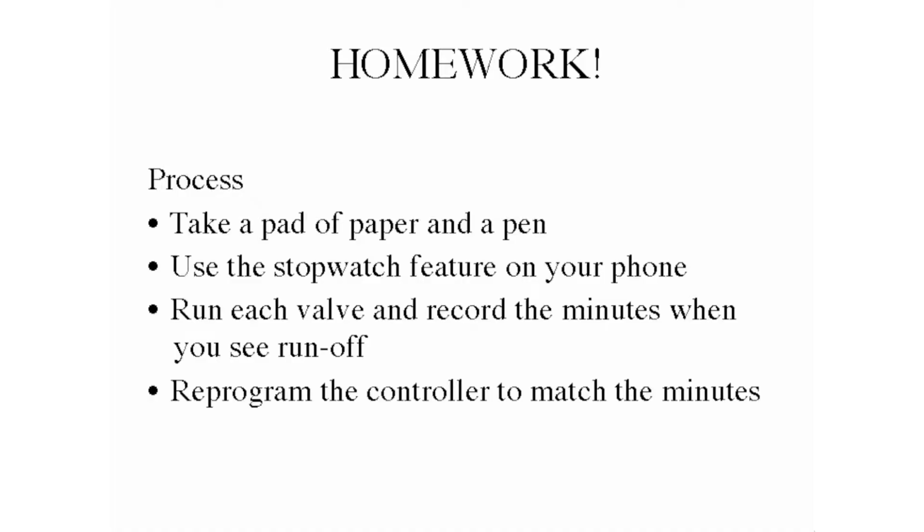So your first homework assignment. You're going to take out a pad of paper and a pen. You're going to use the stopwatch feature on your phone. And then you're going to run each valve one by one, and you're going to record the minutes when you see runoff. So in clay soil, you may see runoff in 4 minutes. That is possible. And you're going to watch it, and you're going to write that down.